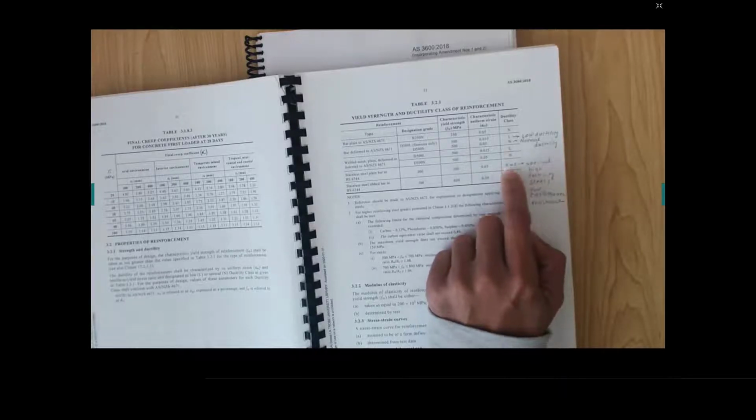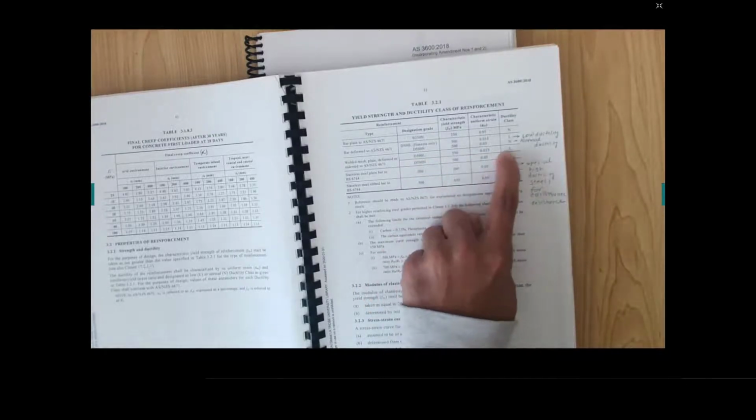New Zealanders heavily use those earthquake resistance classes, but we normally use deformed bar with 500 megapascals with class N over here. This 500 megapascal is the yield strength. The Young's modulus of the steel is given here, clause 3.2.2, 200,000. Okay, so